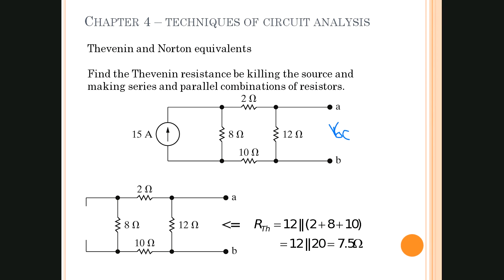Right. So it says find the Thevenin resistance. And so this is just a way of finding Thevenin resistance. So what we do is we just go ahead and kill that load. We don't care what that is right now. And now we just have this parallel network. And so what we're doing is, if I were to hook up the meter to that circuit, what would the ohms read? What would you actually read in the meter? Of course, with whatever tolerances we have, and we can actually calculate that.